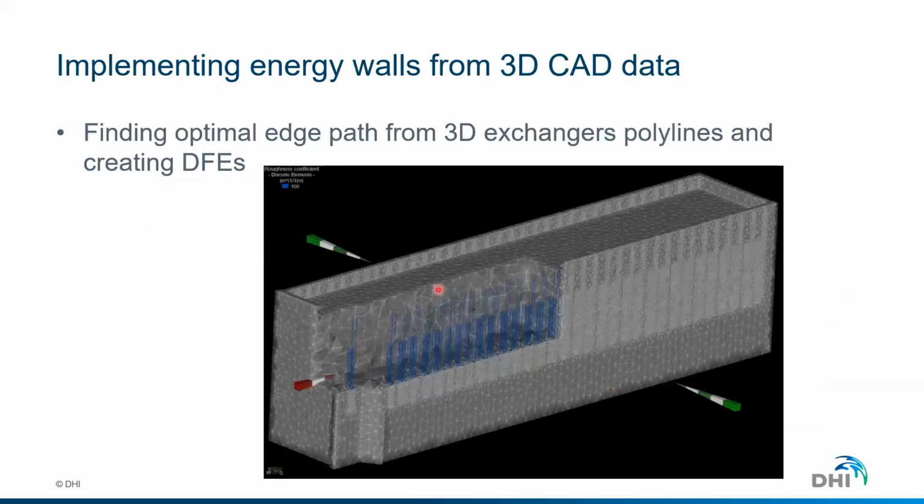And that's the example of the FEFLOW model, including the geometry of the pipe. So not everything is incorporated, but only the major structures are part of the model. And you can see here the model does not have continuity in the layers, so we have a fully unstructured mesh which accommodates the 3D polylines representing the pipes around the different tunnel walls.